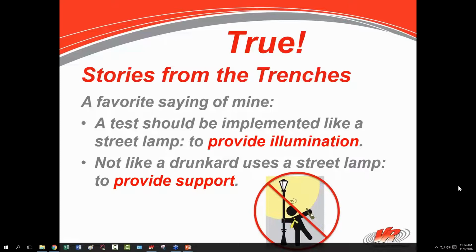So when a test is sweeping and it hits a resonance, hold it on the resonance, walk up to it with your fingers, and you can usually find a spar or a rib. Usually the most common problem is header expanders. You're going to find one that by just the touch of the finger, you can feel that it's resonating like crazy. Not good. And that, of course, is going to affect your test. So you want to get as many of the resonances out as possible, recognizing that, hey, things are going to resonate, but if they're not too violent, you can usually accept them as they are. But that's a good question. That's how you can tell where the resonances are.